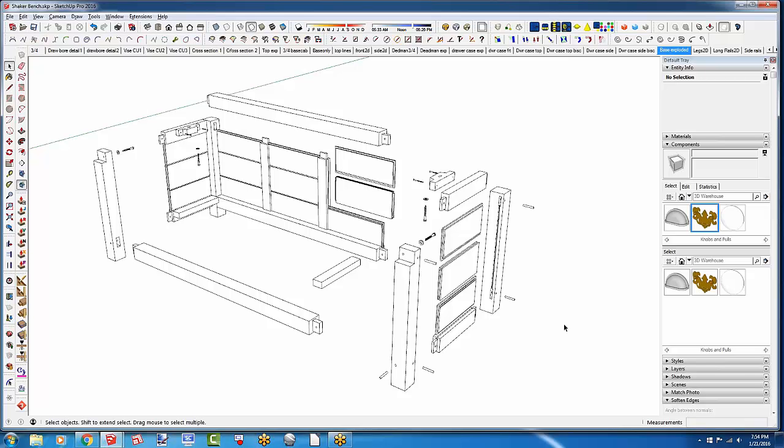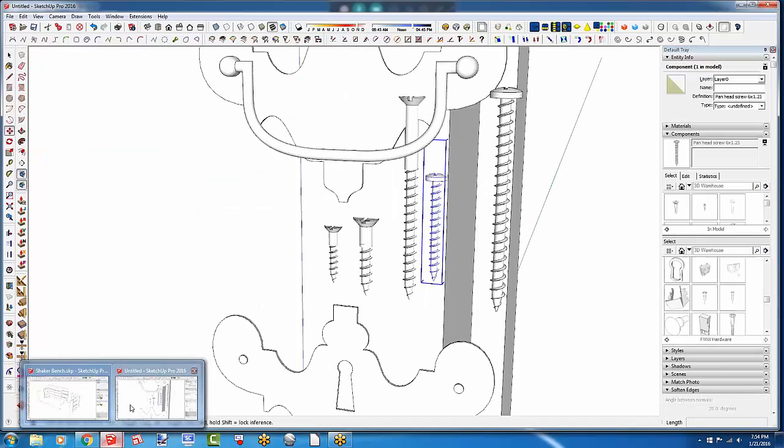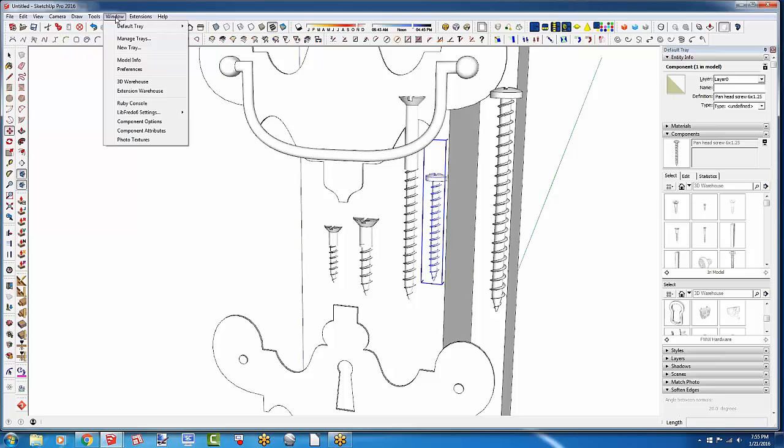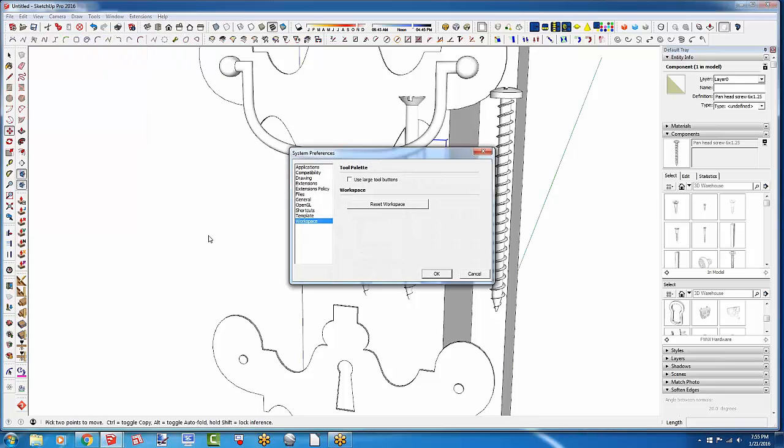One other thing about this business with this in-model library, I've seen some cases where people have had their computers crash, like power goes out while they're working, and some people will turn off the autosave function that you can set in preferences, because they think that it slows them down when they're modeling, because every, say, 5 minutes, SketchUp performs an autosave, which I think is under General.